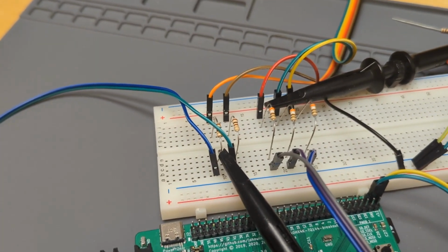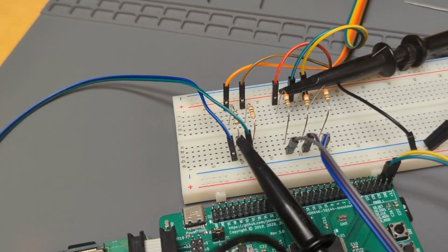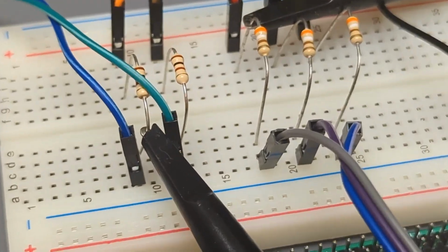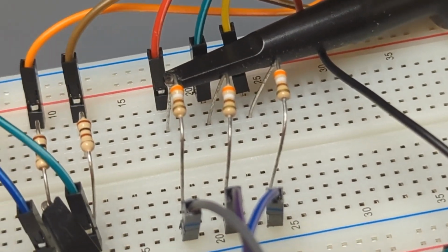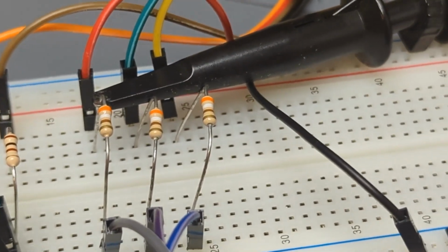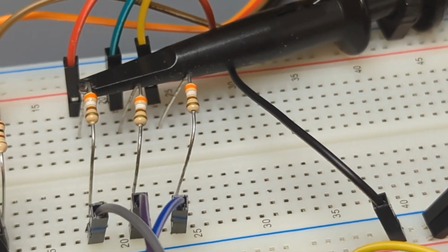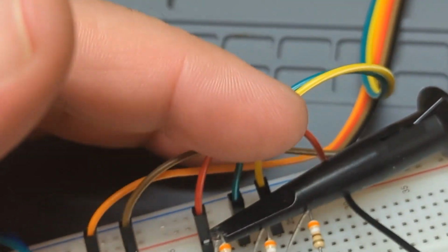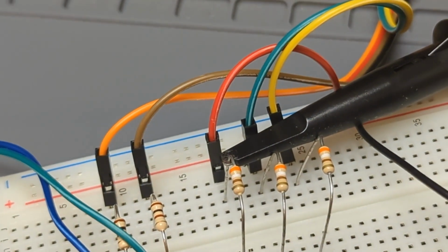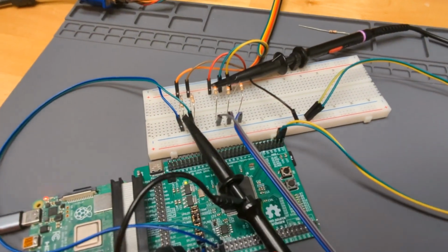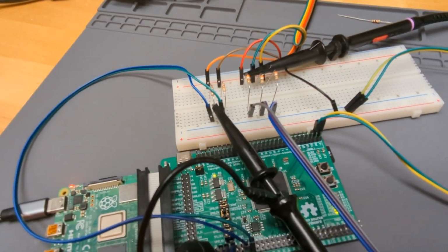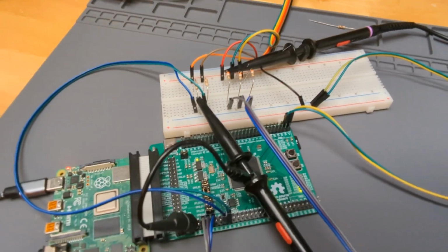Anything at 75, 80, 85, even a 50 ohm, 100 ohm, 110 ohm, those are very nominal. Around 100 ohms is what you want to have on there. Do not put resistors that are too small in series with the outputs for the RGB values, because you don't want to overload your FPGA. These wires inside the video monitor are terminated with 75 ohms inside your display. So the FPGA wants to have at least about 400 ohms or more on the outputs, otherwise you draw too much current, all right?